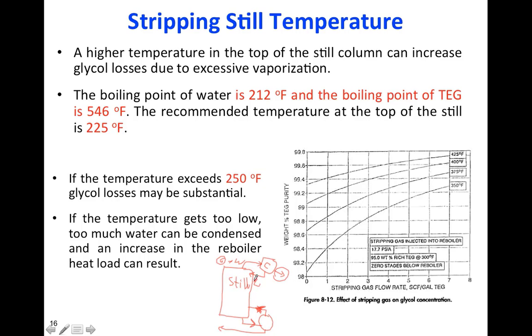When we do this condensation, since glycol is heavier and has a higher boiling point, the glycol goes to the liquid phase first. So we can do some separation here as well. When we condense this mixture of glycol and water, glycol goes to the liquid phase first, so we can extract even purer water vapor here.